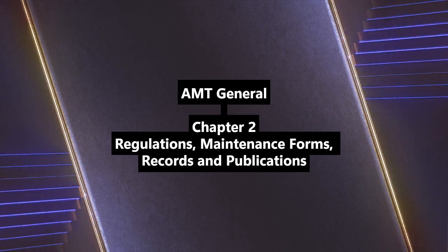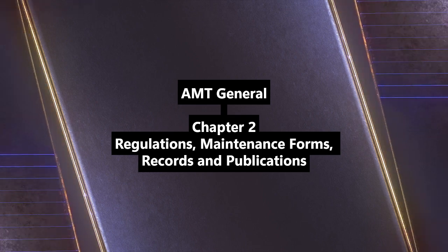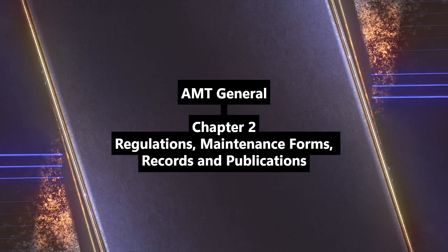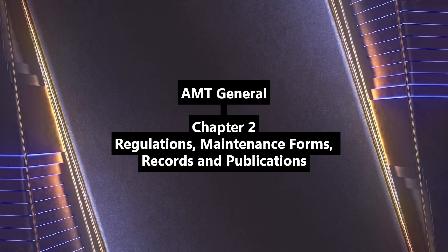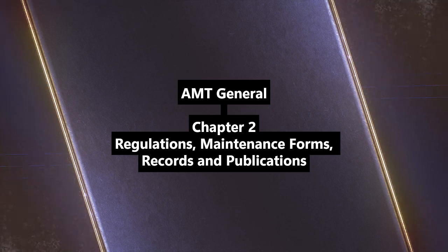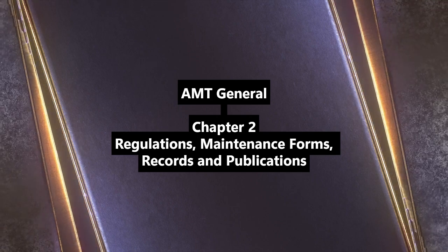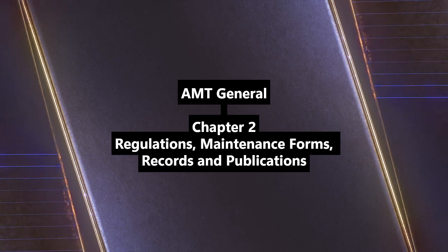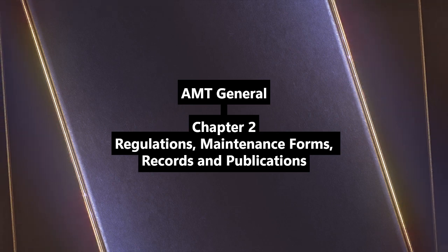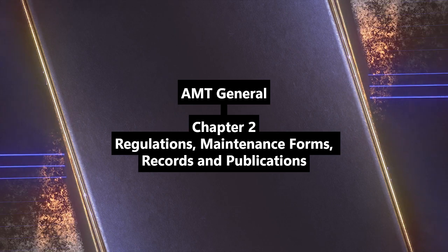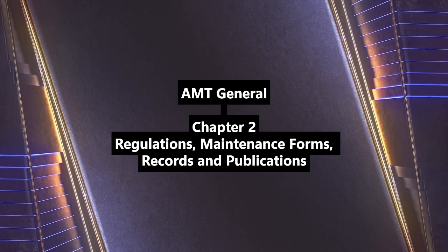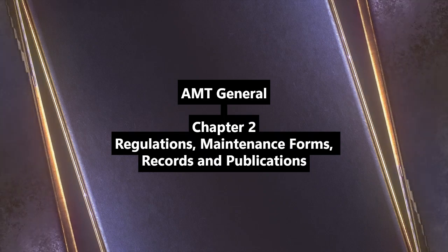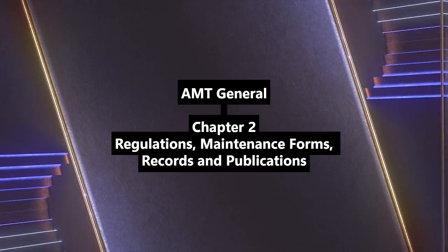What about identifying aircraft and parts? That's 14 CFR Part 45, identification and registration marking. It covers everything from the fireproof data plate on the aircraft with the serial number, manufacturer, model, right, to the specific FAA PMA markings required on approved replacement parts. Parts Manufacturer Approval. And of course, the big N number, the nationality and registration marks. Part 45 specifies the size requirements, which can vary based on age and type. It affects both original and ongoing airworthiness.